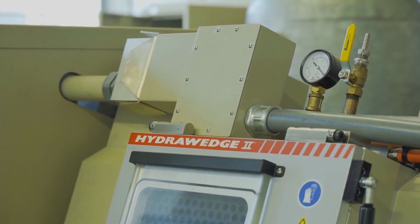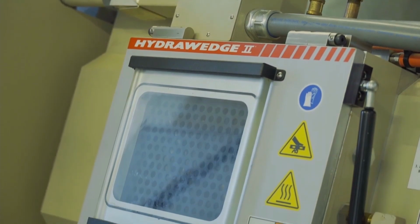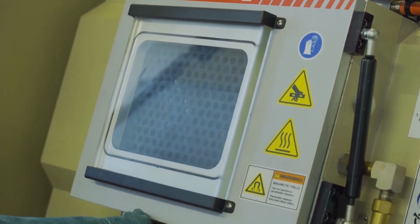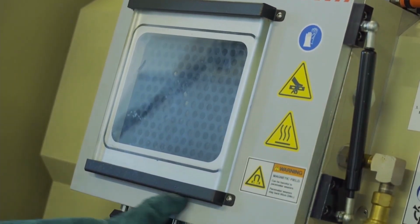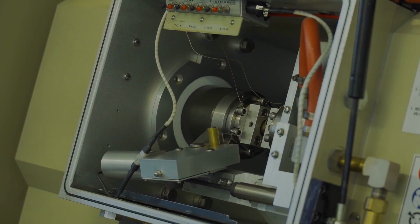Then after that, what we do now is to open the chamber. You press door release on the console, and now you can remove. So now we're going to move the wedge back so that we can remove the sample. And to do that, you press run mechanical on the console and allow the pressure to build up. And after it has built up, then what you need to do is to move the wedge.